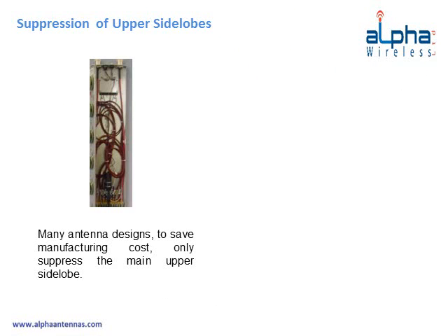Suppressing all upper side lobes across the antenna tilt range can only be achieved when all radiators in the array have their phase independently adjusted. Antennas that adjust the phase in element pairs compromise the upper side lobe suppression and generate lobes as high as 11 dB below the peak.